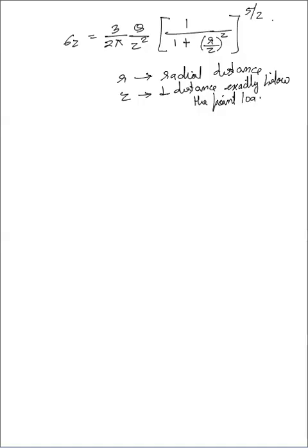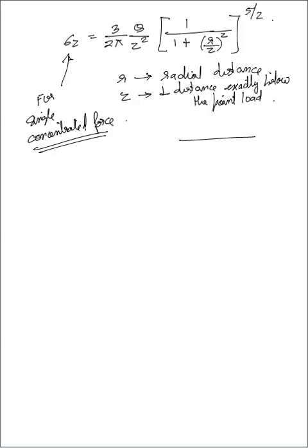By using this formula for a single concentrated force, if one point load, single force is there, we can apply this formula and find the stress at any vertical distance as well as any radial distance, because we have the value of Z and this is the radial distance.